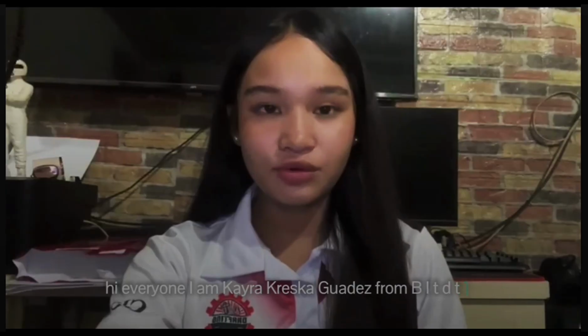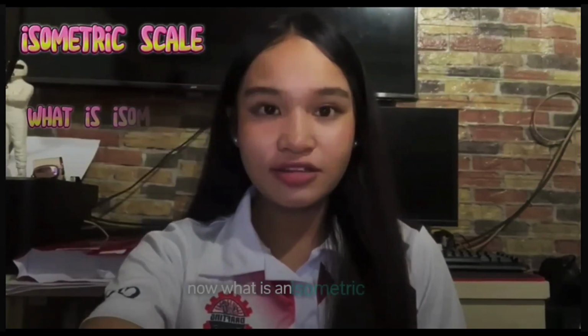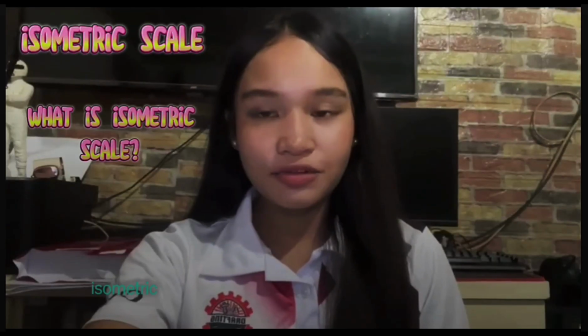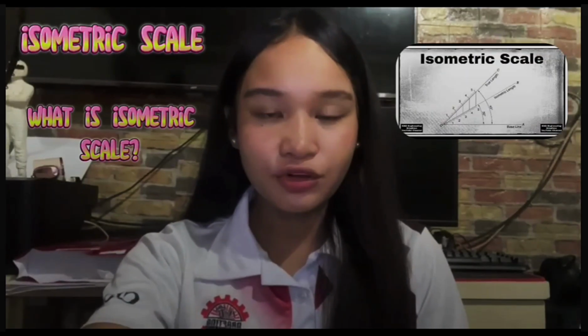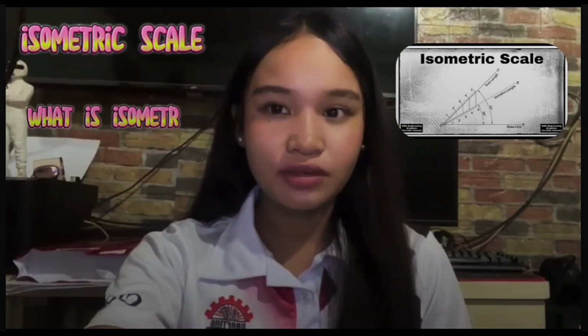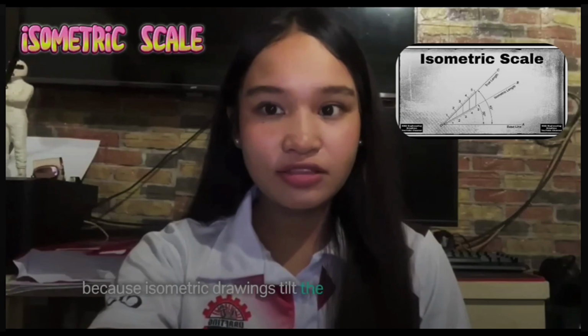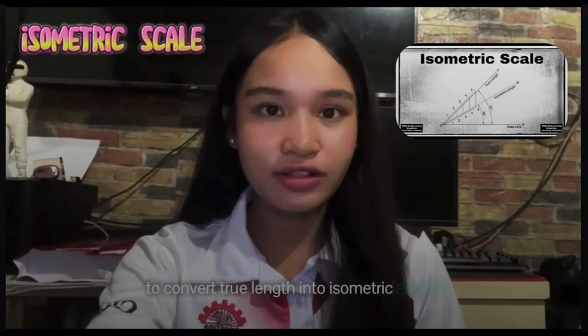Hi everyone, I am Kyra Kiskaguates from BIT DT1B and I will be discussing the isometric scale. Now what is an isometric scale? An isometric scale is a special scale used in isometric drawing to make true measurements look proportionally correct when drawn along the isometric axis. Because isometric drawings tilt the object at a 30-degree angle, normal measurements will look distorted if plotted directly. To fix this, we use an isometric scale to convert true length into isometric length.